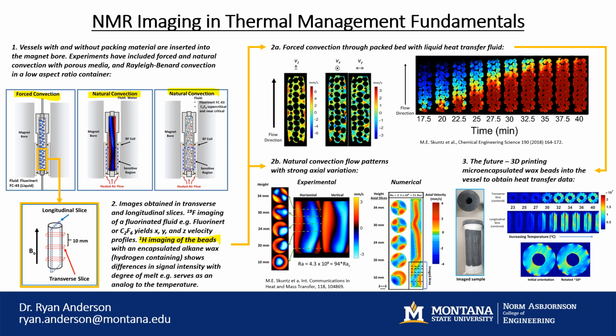What's really important though is that there's the coupling between the heat transfer behavior you're seeing here in the top right and the fluid flow behavior that you're seeing in the center in the top images here. So in this case, we switched the imaging technique to use a fluorinated fluid, so doing fluorine imaging, still fluid flow from the bottom to the top in this case.